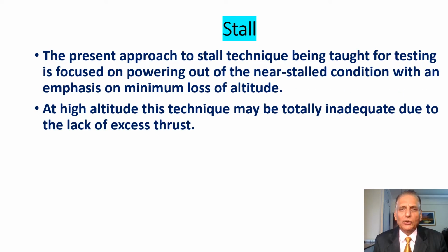The present approach to stall technique being taught for testing is focused on powering out of the near stalled condition with an emphasis on minimum loss of altitude. At high altitude, this technique may be totally inadequate due to the lack of excess thrust.